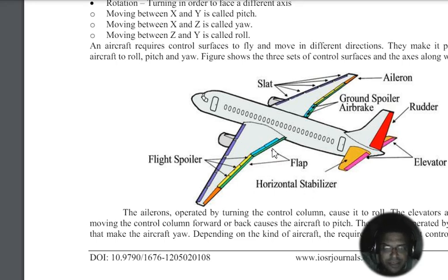Then the third one here you can see is, we have aileron, we do have rudder, and then there are some other mechanism surfaces which are present here, which is called flap. Flaps are responsible for increasing the lift as they go down. Many times you will see when an aeroplane is taking off, a larger surface, a bigger surface at the back of the wing, actually it goes in the backward direction, and it allows more lift.